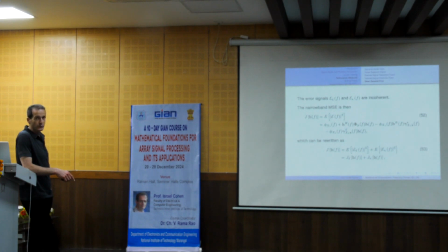By the way, when we compare multi-channel filtering in the frequency domain using this model, you see that we do it for each frequency independently. So you see the length of this filter. What is the length? M, exactly. The number of sensors, which is much smaller than the length of the filter in the time domain for multi-channel.